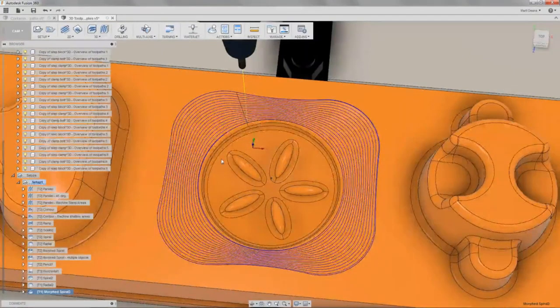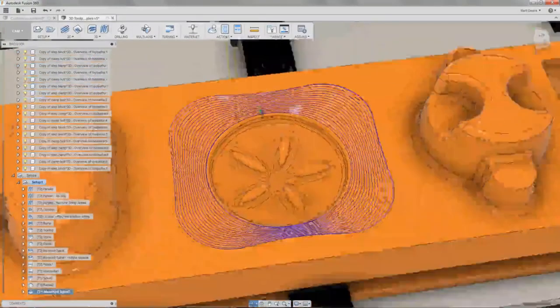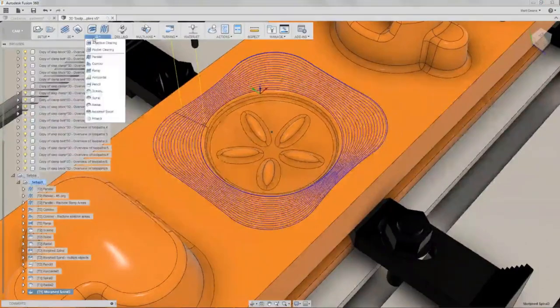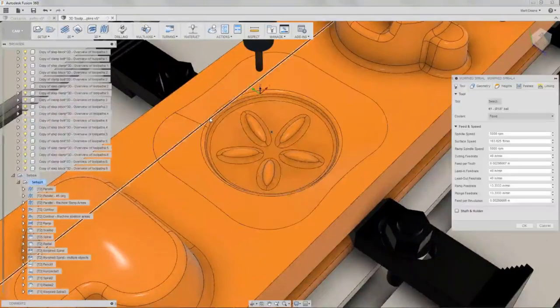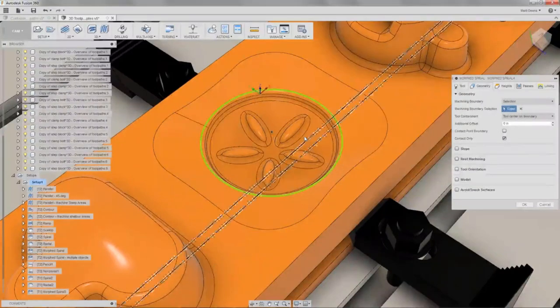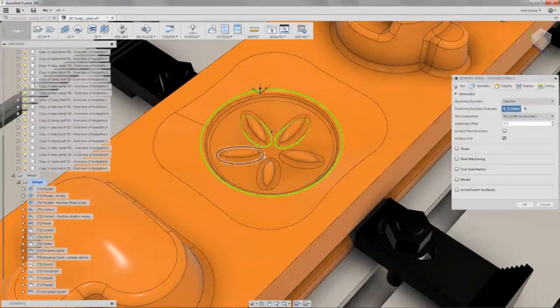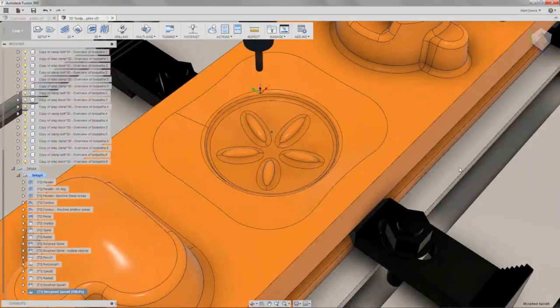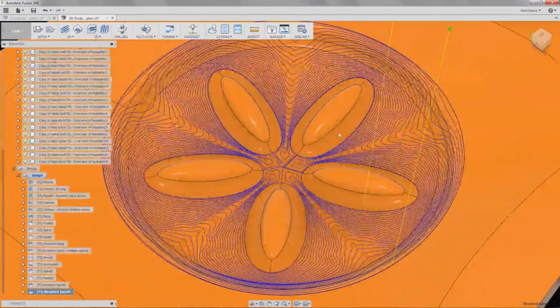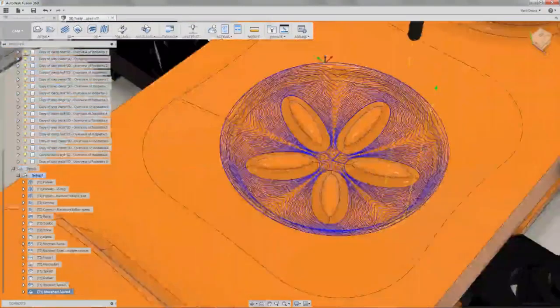It's usually very smooth, really good for organic shapes, but it does require a machining boundary selection. It can also work with multiple shapes. So I could go from this one circle to these 5 petal oval shapes, and it can do that transition. It doesn't look quite as pretty as the one boundary selection, but it will do smooth lines between, like a morph between those multiple shapes.